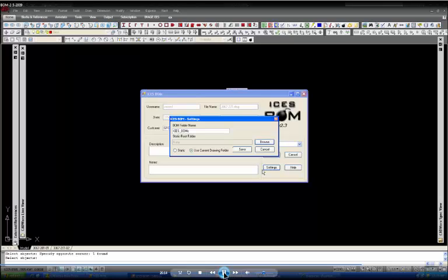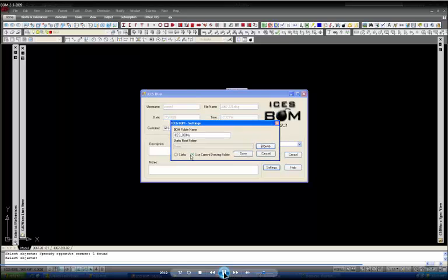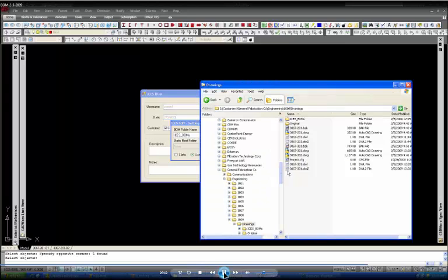Currently, we do have some settings that you're able to save. An example would be on the snapshot. We have two different choices. You can save all of these BOM snapshots to one single folder, if that's something you want to do, or you can tell it to use the current folder where the drawing is located, and then create another folder named whatever you type here, and that's where it'll place the BOMs. So looking at how that's set up, you can see that we've got drawings. Here's my drawing.